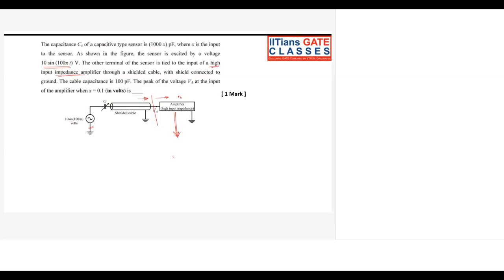So if you see that internal circuitry, then some input resistance is there, and then we have the open loop gain. This is going to be AOL into VID. So you will find the differential voltage here, and then you are going to get V naught. Our main motto here is that we don't want to take the chance of any loading effect. So whatever the circuit is here, this circuit should not load this part.